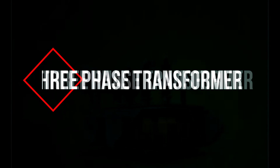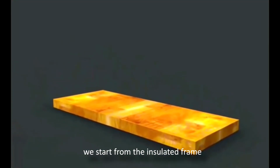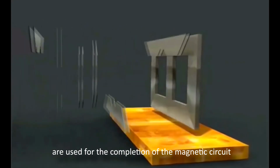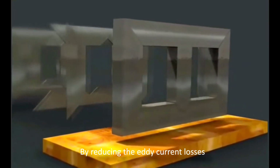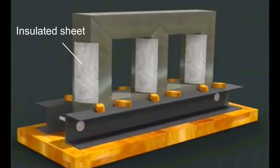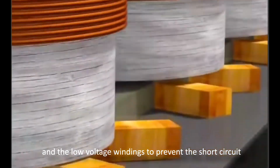How to solve all these issues? People build three-phase transformers to solve all these issues. To build a three-phase transformer, we start from the insulated frame. Laminated and well-insulated iron core is used for the completion of the magnetic circuit and to reduce the eddy current losses. By reducing the eddy current loss, we can reduce the electrical energy being wasted as unwanted heat energy. Insulated sheets are used between the high voltage and the low voltage winding to prevent a short circuit.